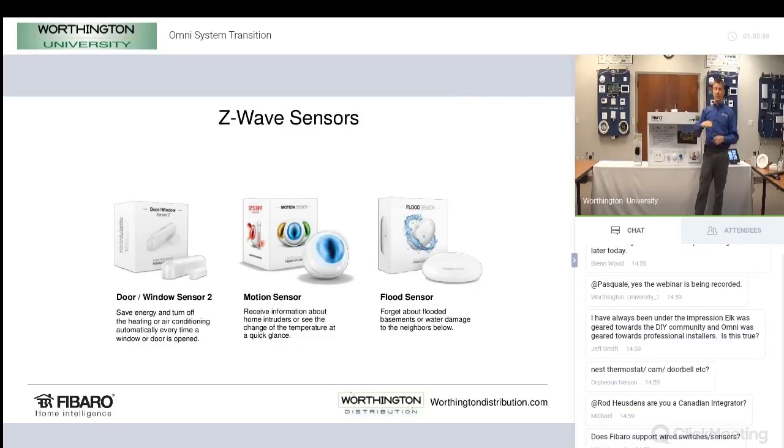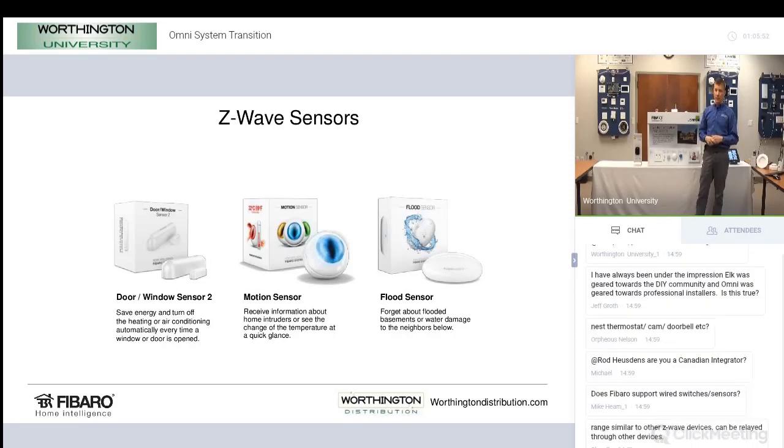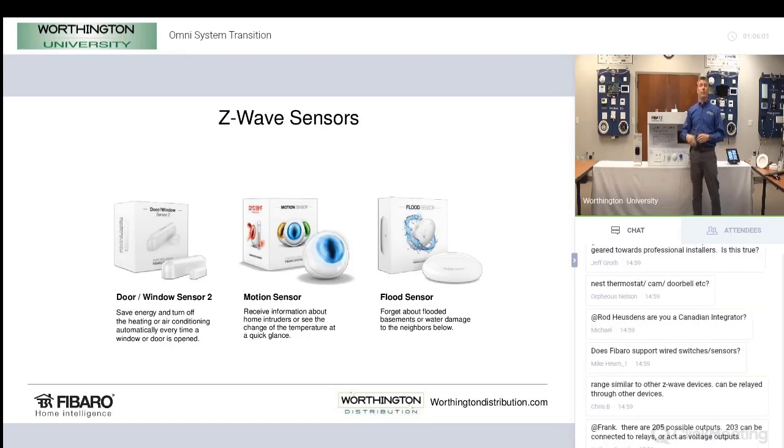Well, with the temp sensor, in a lot of situations, we can. So by sticking this flood sensor, let's say in the basement by the water heater, which is a really common area for it, we can also write a rule that says if that flood sensor sees a temperature below 40 degrees Fahrenheit, let me know about it, and maybe we can preempt the freeze-up and solve that problem altogether. So it's nice that we've got those temp sensors and everything.